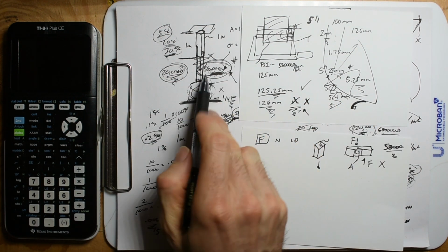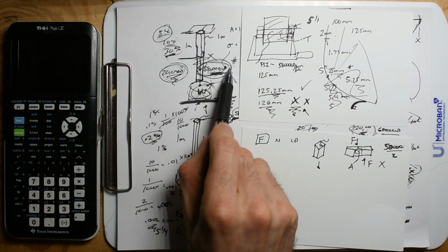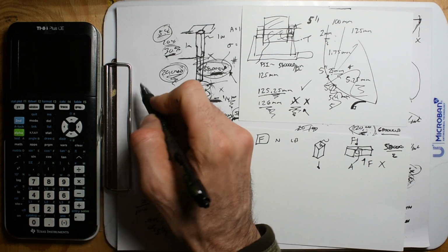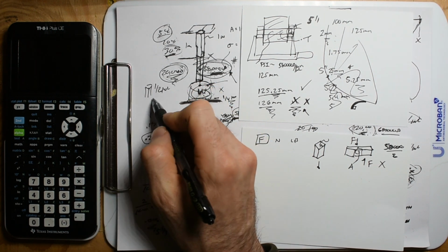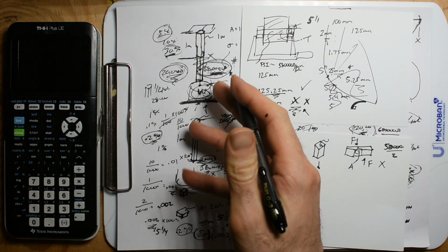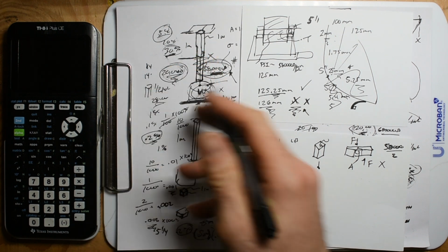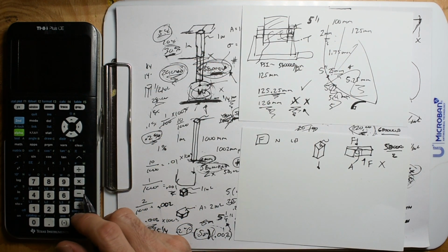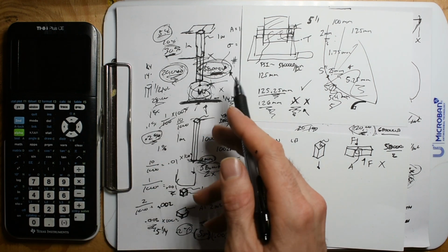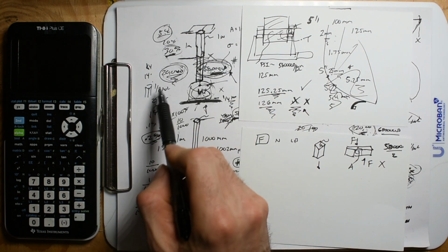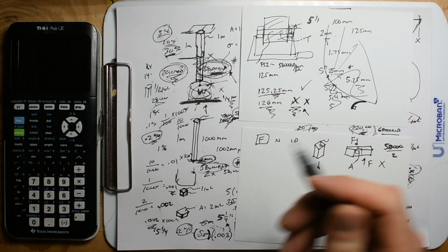And so it's good to have in your mind that I chose a 1-inch steel rod because I can put 58,000 pounds on it. Well, if I just have a half-inch area, inch squared, I can put 29,000. Quarter-inch, it'd be half of that, about 14,000. And so forth. Hell yeah, and that's an easy fraction. There are a lot of different mathematical ways to make a simple equation. It's just a linear equation, and it literally starts at 0.